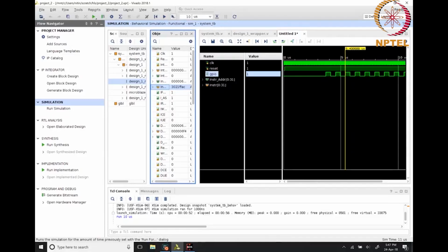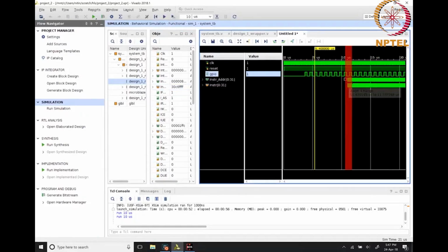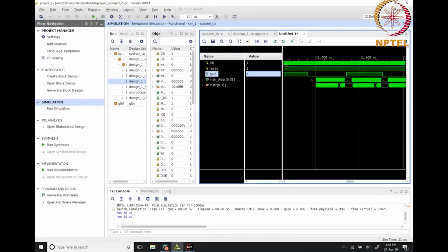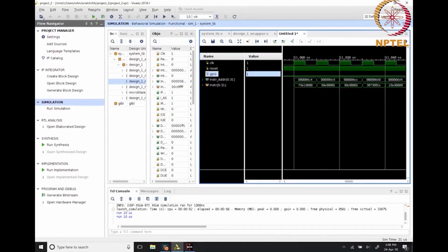You can either relaunch or just continue to run a little bit longer. And you will find that when you zoom in over there, you can actually see the instruction addresses changing. And if you look at the addresses carefully, you will notice that on every clock cycle, they basically change by 4, which is 32 bits or 4 bytes. And on every clock cycle, in other words, a new instruction is being read in. The actual instructions are there below. You probably can't really interpret them unless you know the machine language of the MicroBlaze, but the information is available to you if you want it.